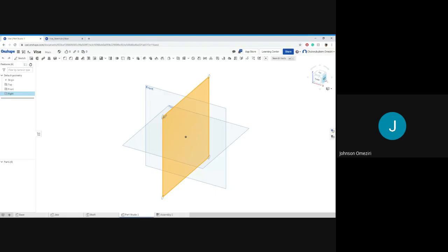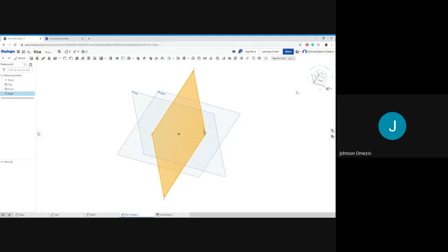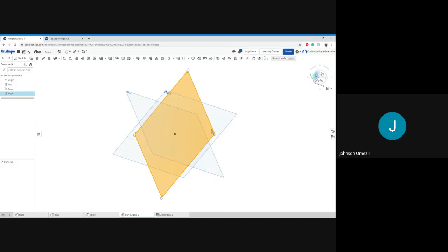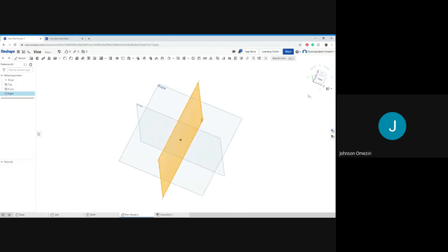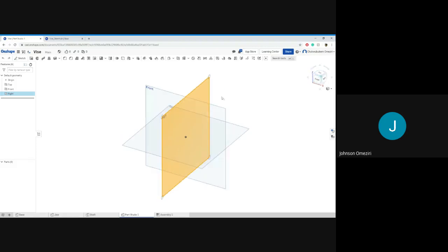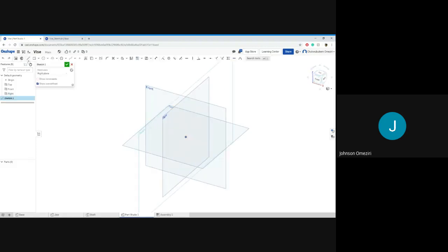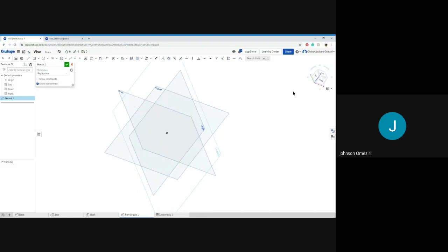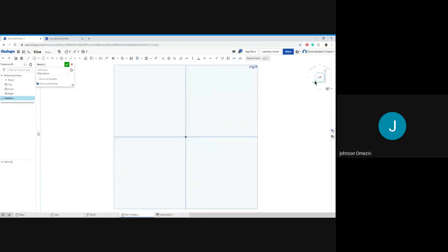This one will be better from the left, so maybe click the left this time. If you want to, you could just click the right again. Click the right plane. Click sketch. Then turn around and click left. If you see now, the right is spelled in reverse. It means that we're facing the back of the right plane, not the front of it.